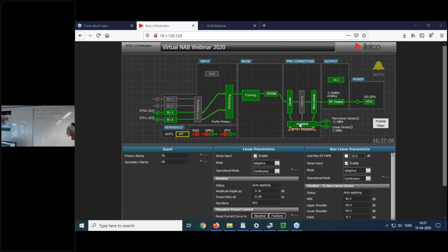I will just show you what I was mentioning about the nonlinearity or memory effect of the transistor. We have noticed that for a transistor to enter saturation, coming from a linear region, requires less energy than taking a transistor out of saturation.